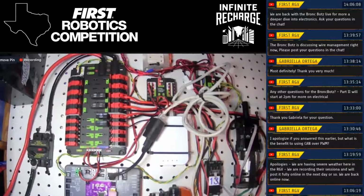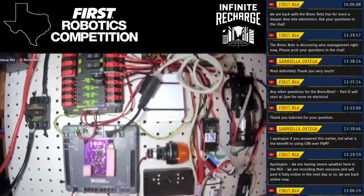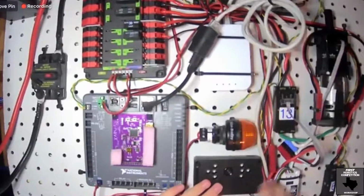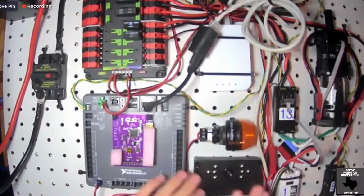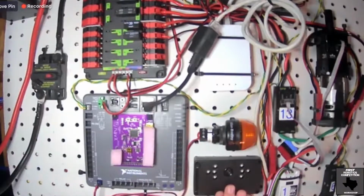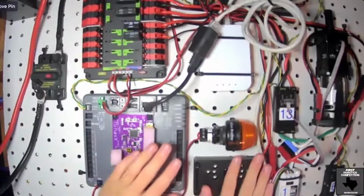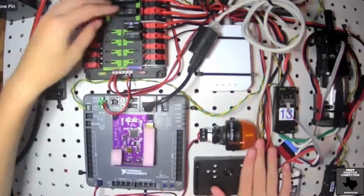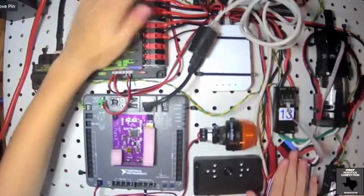Another example, I've got a Limelight plugged in right here. This actually does not get plugged into the VRM. This wire goes straight into your PDP. You're going to want a 20 amp. I believe the website actually calls for a 5 amp breaker, but we don't use that. So this is a 20 amp breaker plugged in right here. And then I have a motor controller on a 30 amp breaker, and the other two motor controllers on 40 amp breakers.